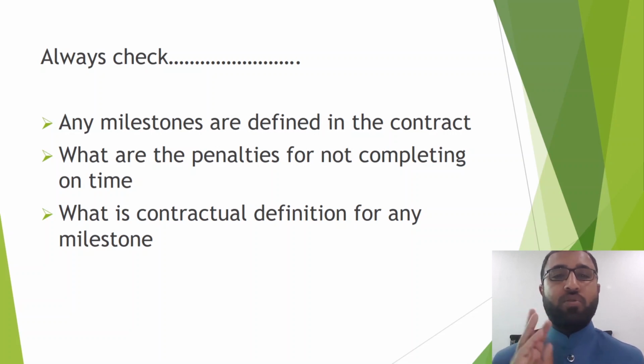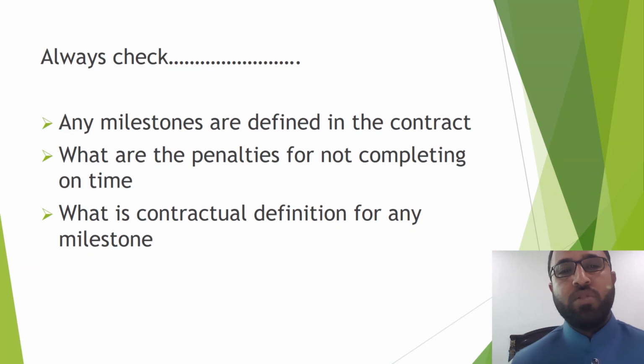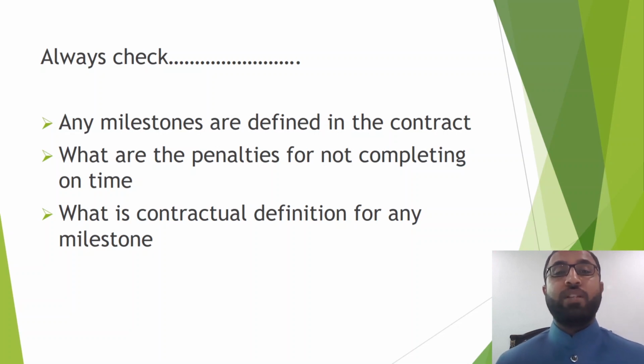What are the conditions? All the doors should be installed, the first and second coats of paint should be done, the last coat can be done later on, all the ducting should be completed, and the wild air should be on. All the MEP first and second fix works should be completed, without lighting. All the floor tiling should be laid. No dust should come inside whilst the nominated subcontractor is working. So these were the requisites for that milestone, the dust-free milestone.